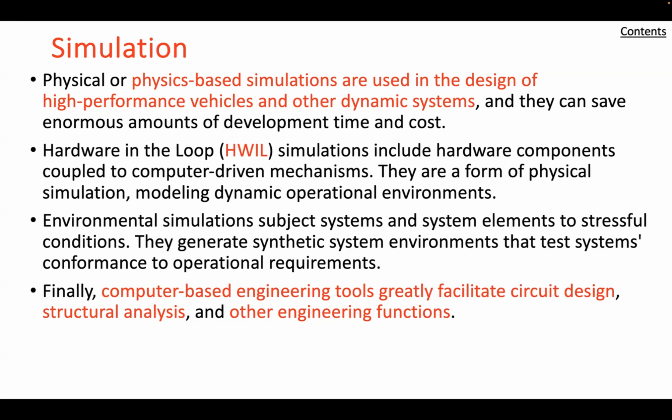Few technical problems are as complicated as the design of high-speed aircraft. The aerodynamic forces are quite nonlinear and change drastically in going between subsonic and supersonic regimes. The stresses on airplane structures can be extremely high, resulting in flexure of wings and control surfaces. There are flow interference effects between the wings and tail structures that depend sharply on attitude and speed. Simulation permits all of these forces and effects to be realistically represented in 6 degrees of freedom models, 3 positions and 3 rotation coordinates.